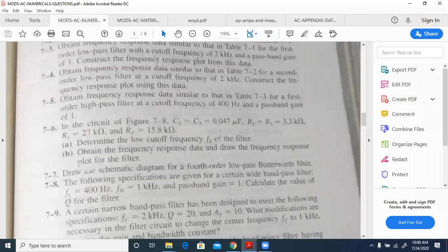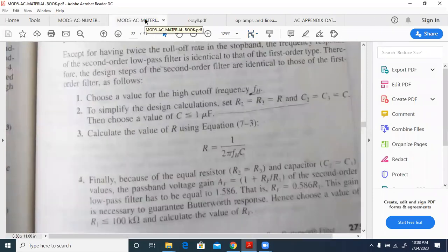Having chosen the value corresponding to that, we can choose the 2 kilohertz frequency there. So R will be equal to 1 by 2 pi times 2 kilohertz times the value of C chosen there, which might be 0.01 microfarad. Whatever you get over there, approximately, you can choose the nearest value, or you can use a potentiometer in place of that, and complete it.